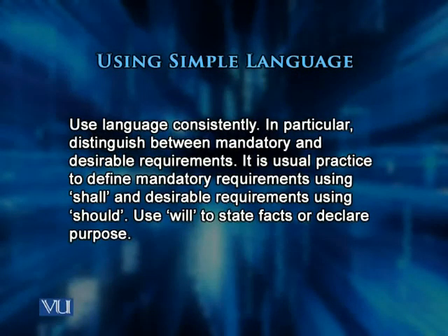It is a usual practice to define mandatory requirements using the shall statement, and the desirable requirements with the should statement, and will is used to state facts or declare purpose. So if I use shall as a mandatory requirement, then any reader will have no confusion between the word shall and the word will. Shall will always mean mandatory requirements.